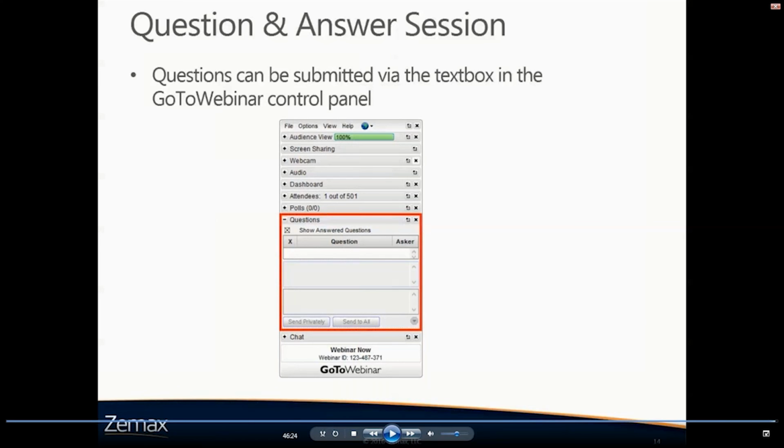The other option is that you can use filter strings to accomplish that as well. When you're looking at your detector data in your detector viewer, or if you have saved your ray trace, there's an option when you run the ray trace to save rays, and it saves to a ZRD type file. Once you have that ZRD, you can also filter in your layout plots. We have a whole section in the help file titled the filter string, so if you search those words, you'll see all available filters. There are filters available to filter for rays that did not scatter.